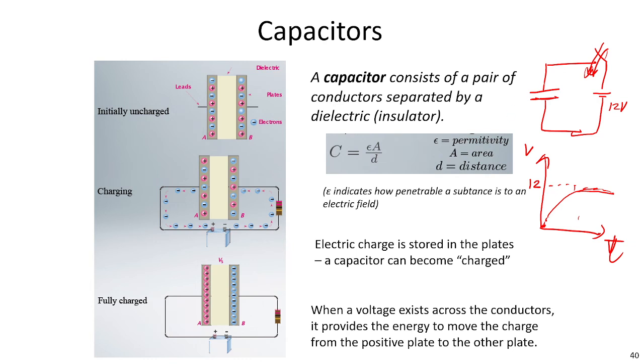It becomes an open circuit because the voltage across this path is 12 volt, similar to the source here. No current flows anymore. If you draw the graph for the current, when we first switch on, there is some current to the capacitor. After a long time, the current becomes 0, like we open the switch for the capacitor.